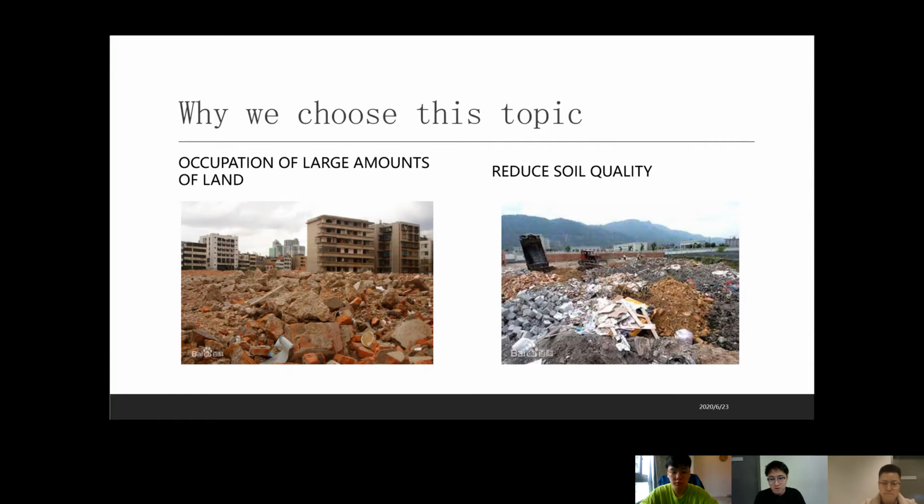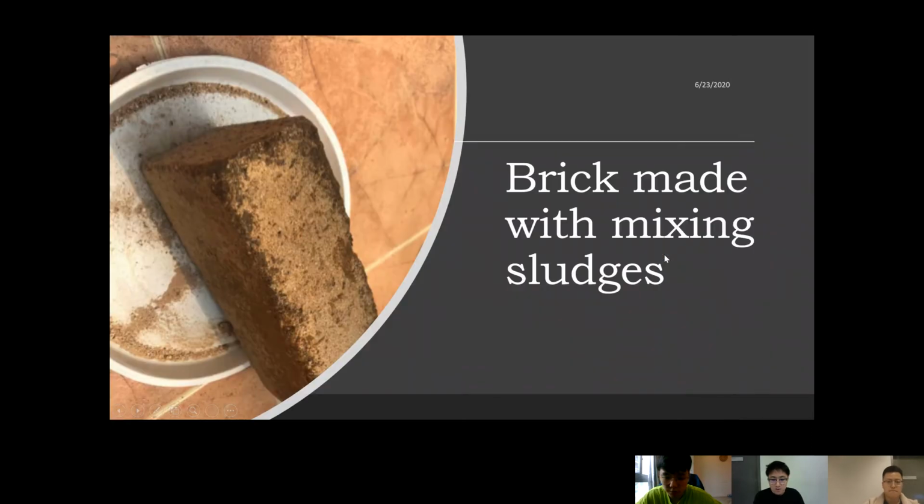In the selection of the construction waste, we chose to use waste concrete and break it into aggregate, which can be easily added to the clay. In the selection of the organic matter, we chose river sludge. With the construction of the city and the development of industry, most rivers have a large amount of sediment deposit. For this sludge, we chose to dry it for up to 10 days under the sunlight to kill the harmful microorganisms and deodorize.